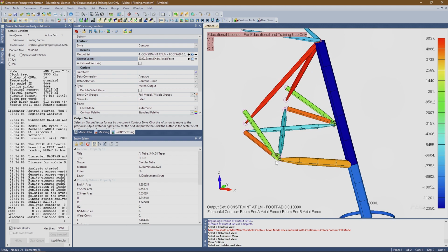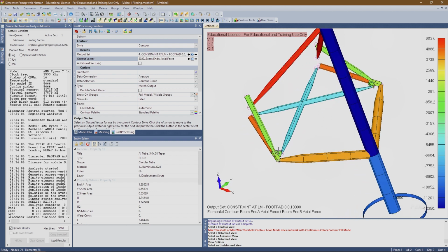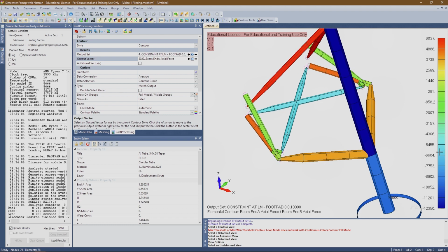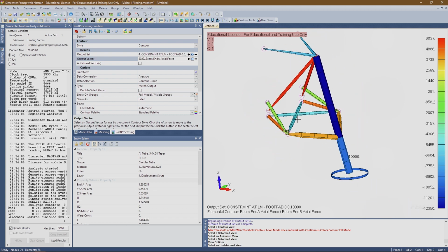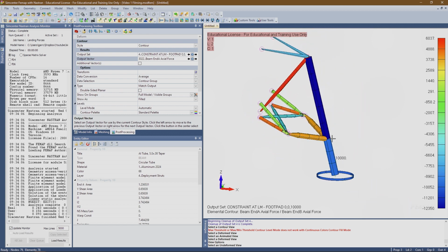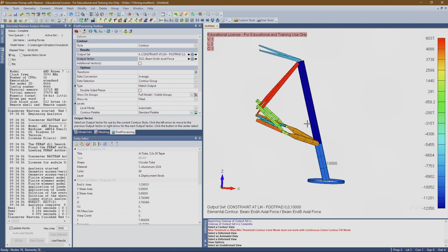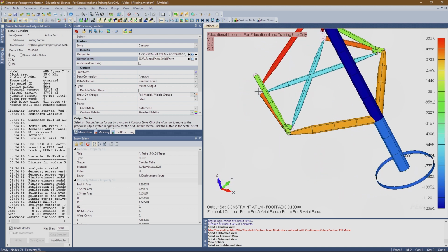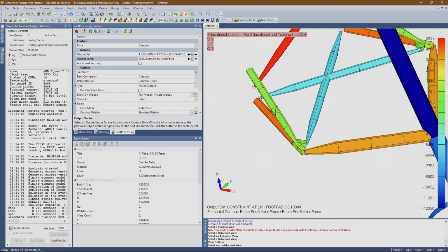Again, jumping in here a bit more, the whatchamacallits, the cross members are in compression. You can see they're blue, which is negative 5,000. That makes sense, right? Because if these guys are in tension as they try to constrain this from getting pulled around, that means that the triangular assembly here is getting pulled inward.